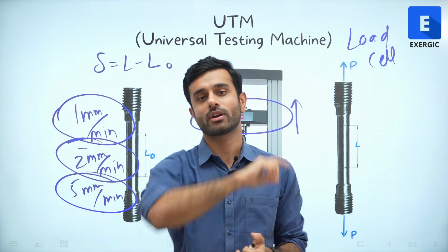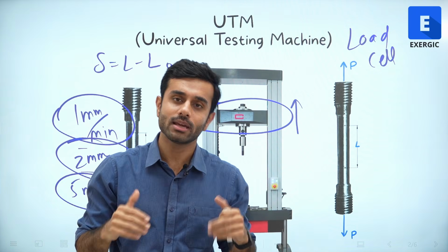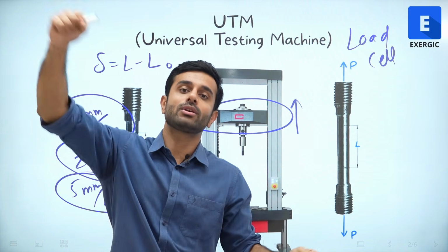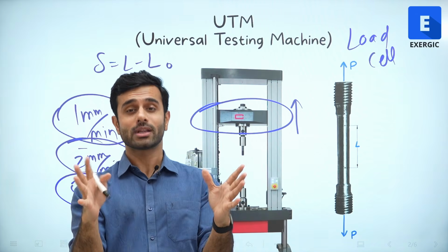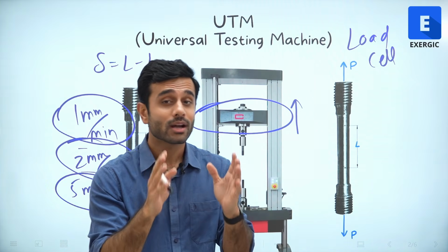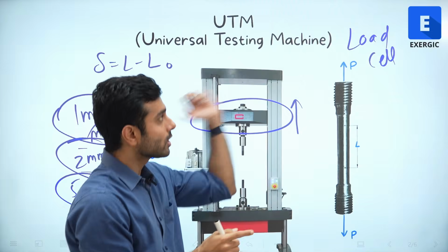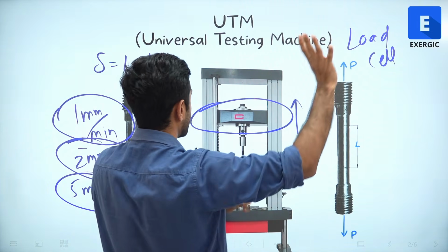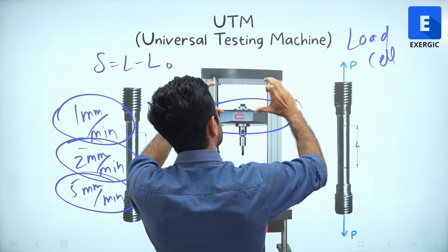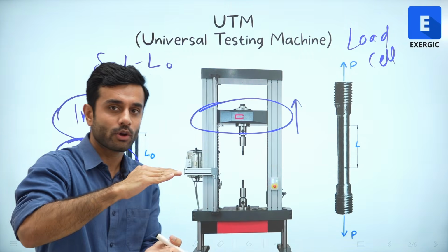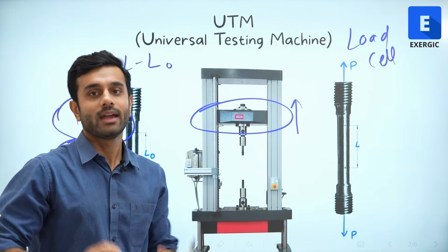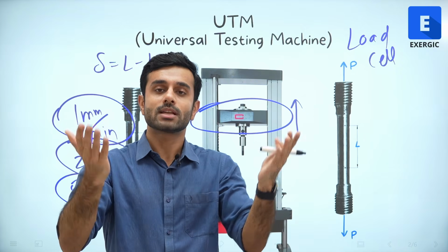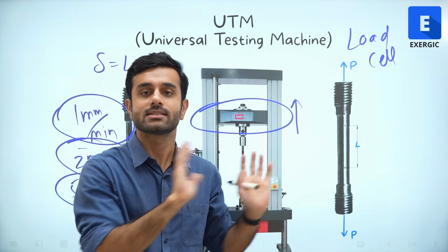This is so important for you to understand, because many students keep thinking that we apply a constant load or we apply increasing load till it fails. Not at all. We do not control the load. That is not our input. This is our input. No matter how much load is required, we don't care. We will make sure that it moves at a constant speed. The deformation is happening at a constant rate. And for that, sometimes it will require more force, sometimes less force, sometimes the same force will be required. That we will see.